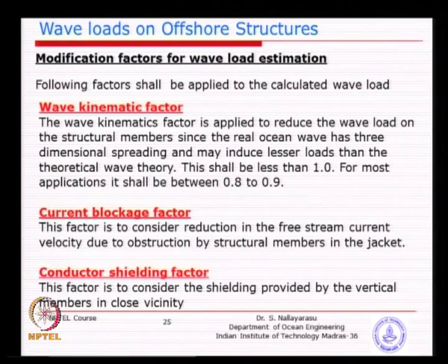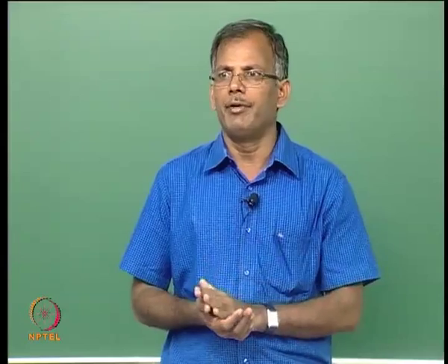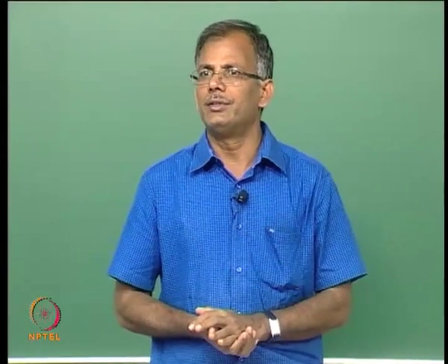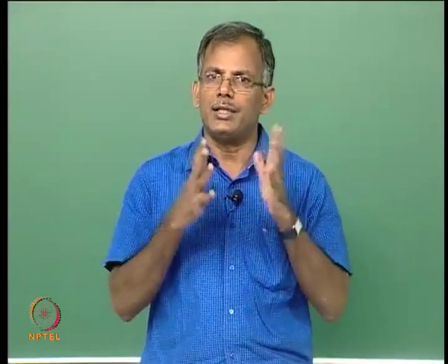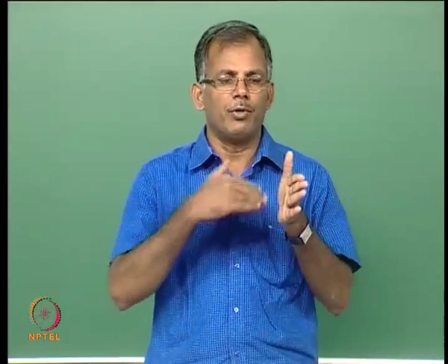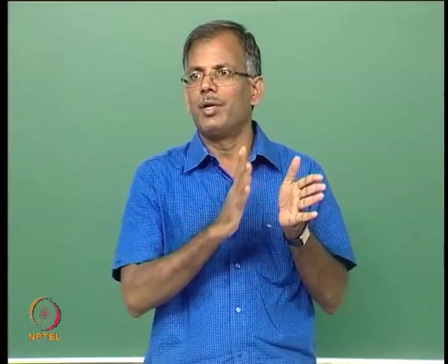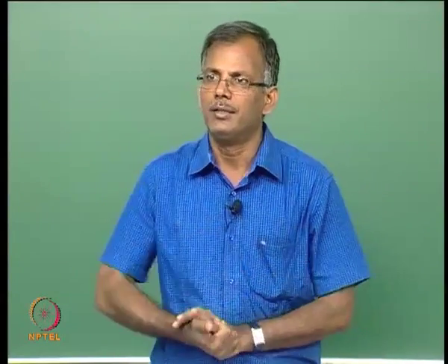So, these other three reduction factors which I mentioned, we should consider. The first one is the wave kinematics factor, very important. What we have seen is a two dimensional wave theory, with the equations, and if you compare with reality, you could see that the water particles are not going to flow in such a nice manner because of the three dimensional effect of the wave.